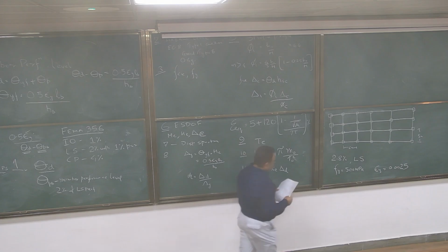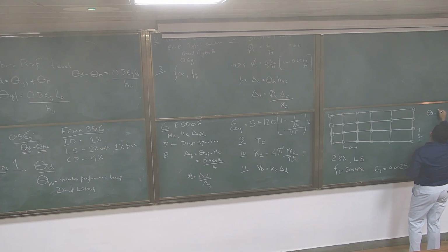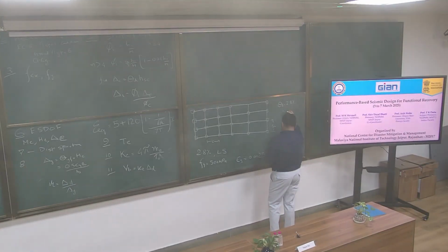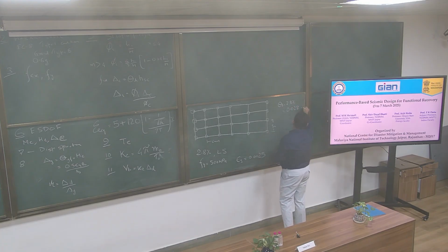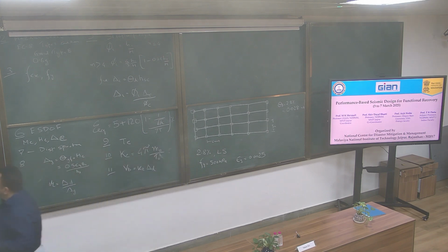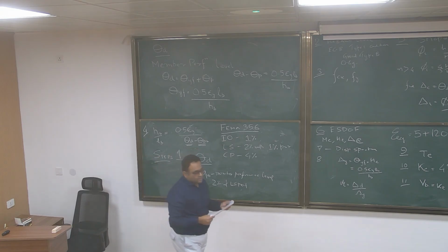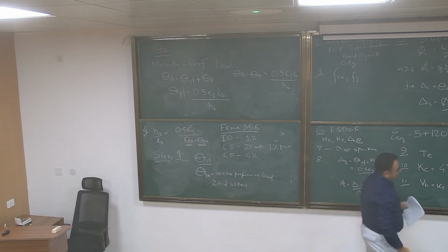So our theta D is 2.8%, which could also be interpreted as 0.028 radians. Now to use this equation where we can try to find the HB over LB ratio, we have theta D, but we also need theta PB. So what information do we have to find that out? We have life safety, right?